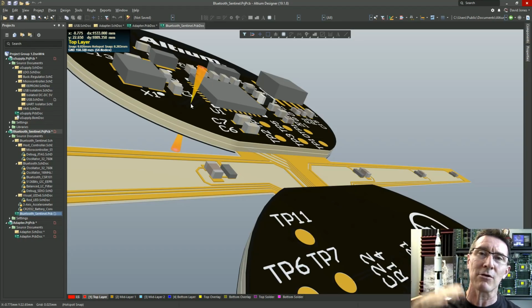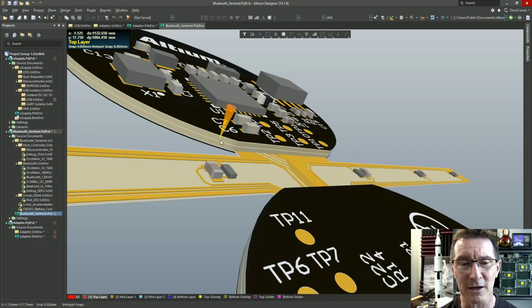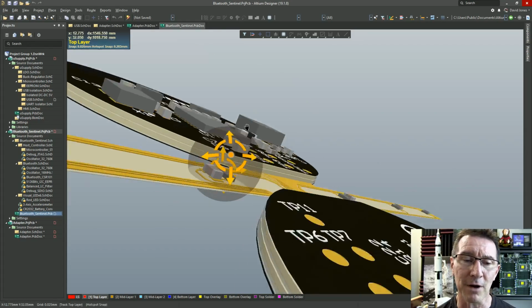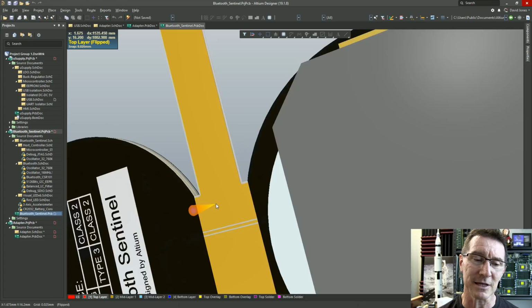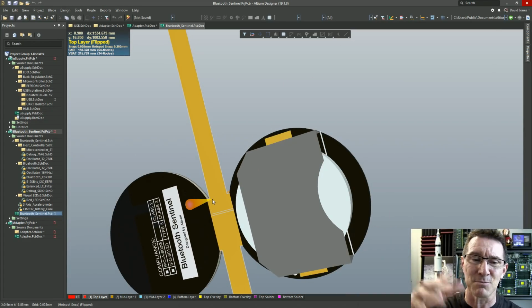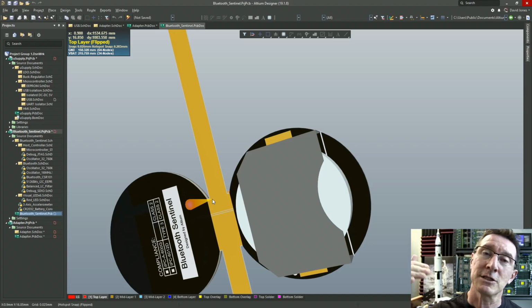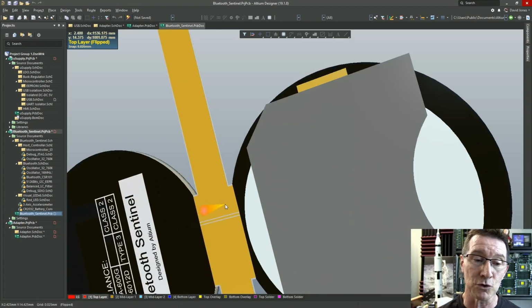Now, as I said, ordinarily you would sandwich it in the middle, so it'd be the inner 2 layers of the PCB, because ordinarily I wouldn't recommend that you put it on the outside like this one, because it doesn't flex. There's more stress and the adhesion can come off and stuff like that. It is more rigid, no pun intended, I'm here all week, when it's sandwiched in the middle. But you can put it on the bottom like this, and the manufacturers will do whatever you want.